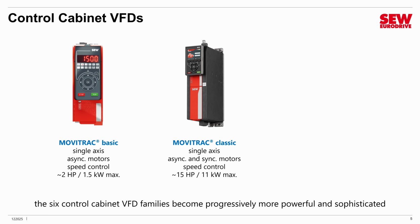MOVITRAC Basic and MOVITRAC Classic are kind of the intro-level VFDs down at the bottom end of the control cabinet branch. They are single-axis. They're generally kind of on the smaller side, so they're meant to run small to maybe medium-sized motors. You can see the maximum horsepower size of MOVITRAC Basic is around 2 horsepower. The maximum size on MOVITRAC Classic is 15. These are what we often call shaft spinning VFDs. They're meant to run those simpler applications where you're just turning a shaft, like fans and pumps.